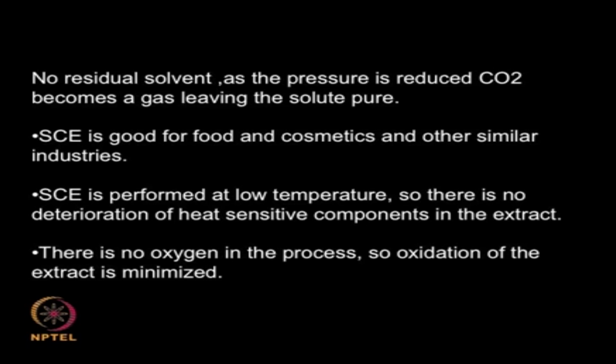In a CO2 system there is no oxygen coming in, that means you are not going to have oxidation of the extract. So practically there is not going to be any oxidation happening. Rancidity happens because of oxidation, formation of peroxides and so on. So such things which normally are found in food products will be very absent when I resort to supercritical CO2 type of extraction.